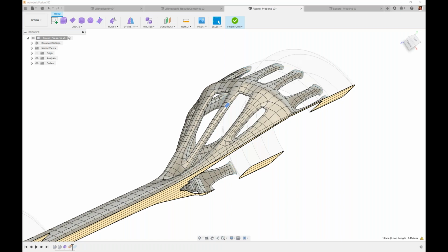Similar to what I was showing here, after you set up the first one, you could clone that generative model and then have a different ID or OD for the given load conditions, and then run all of them to see how that influences the results.